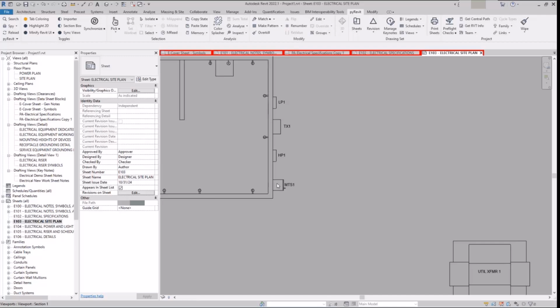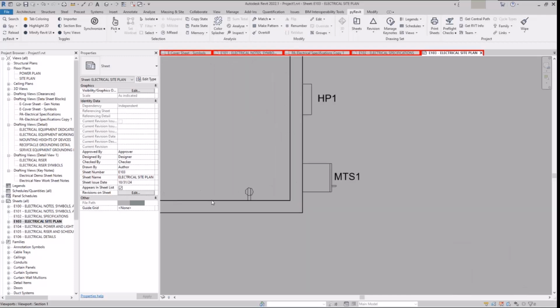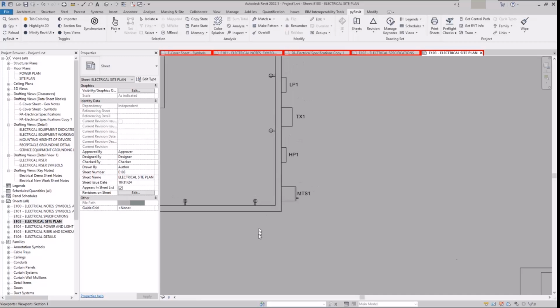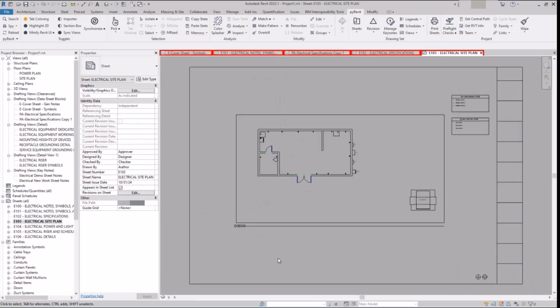What materials do you want me to use? Is there anything dumb in here? Like, I want you to run a number 8 to this receptacle. You can't physically fit a number 8 into the back of the receptacle, so you can't physically build that. Story behind that, not going to get into it, but concepts like that is what the contractor's hat is supposed to be representing.